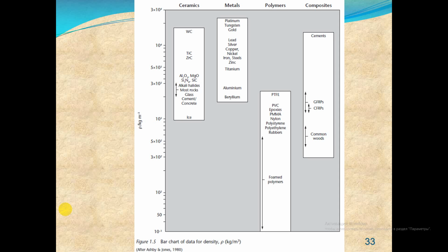Porous materials containing moisture will equilibrate with their surroundings and absorb moisture from the atmosphere during times when the weather is wet or humid. Similarly, they will then dry out when the weather is dry or less humid. This effect causes expansion and contraction effects, in addition to those caused by temperature variation.